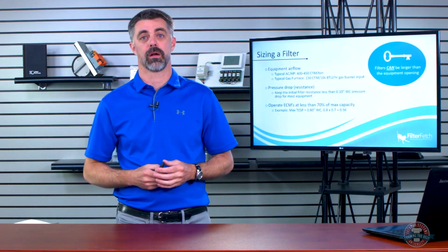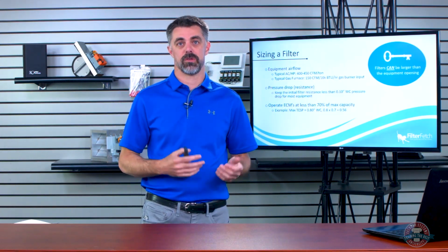Sometimes, depending on the blower style, it's going to use more energy. Sometimes it's just not going to move enough air for the equipment to operate properly. Again, shortening the life of the equipment, potentially damaging things, costing your customer money.